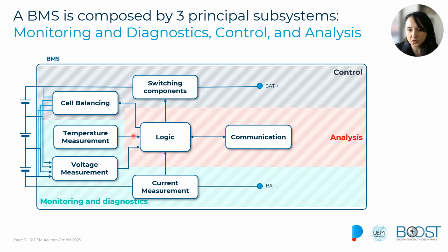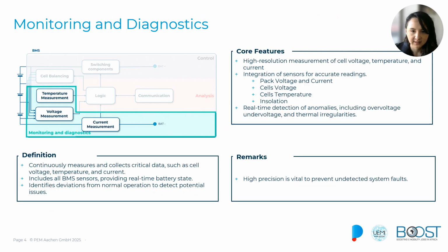We will describe each of these subsystems in detail in the next slides, starting with the monitoring and diagnostic subsystem. This subsystem, as was mentioned, is responsible for the measurement of all of the critical parameters like the voltage, temperature, and current. Basically, it continuously collects and analyzes the data so that it can ensure that the battery is operating within the safe limits.